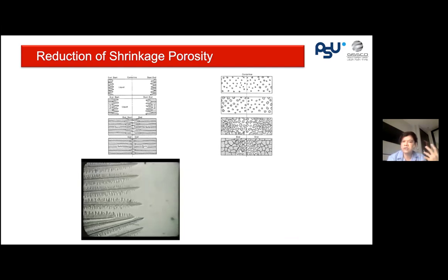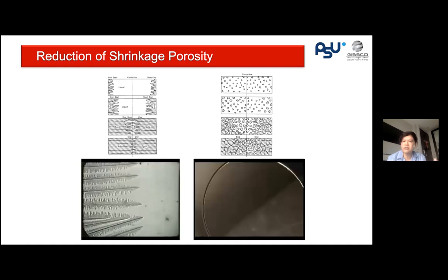But for the slurry that we have, we start with particles everywhere. So these particles will grow spontaneously under this cooling rate with the colder state. So you can see that we will fill all the section like this. So that allows us to reduce shrinkage porosity and then also eliminate the leak path because we change the mode